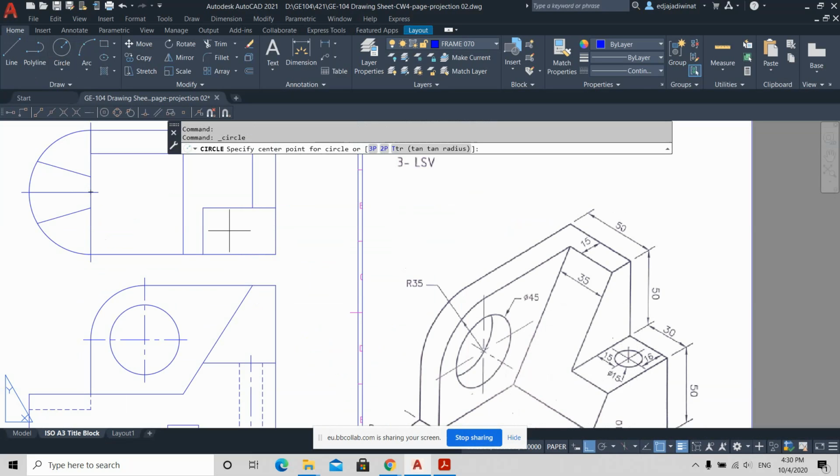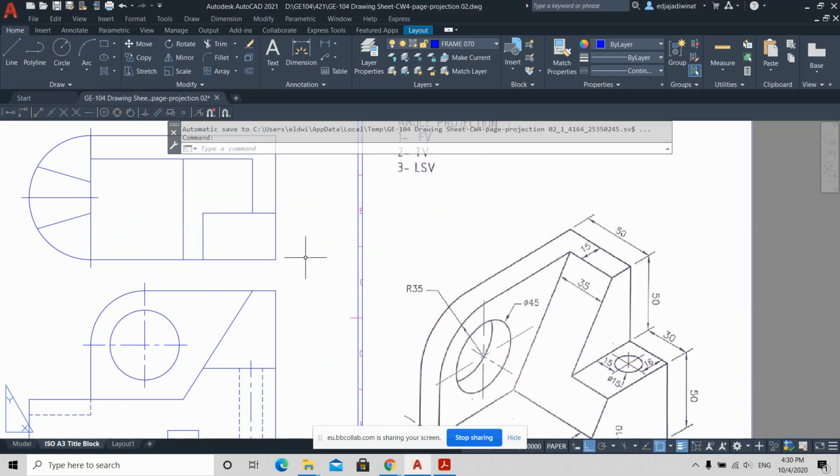You need to find first the location of the center as usual. You can use the helping line, or you can use offset. Okay. If you want to use the helping line, you go from here, it will be comma add -16, because it's -16.